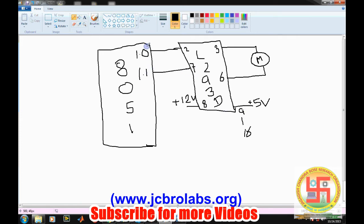Now, in order to decide what should be sent to these pins of port 1, we know pin number 1 and 0 have been connected to the microcontroller. When we send 1 here and 0 here, plus 12 will appear here and 0 will appear here, so the motor will run in one direction. If we set command 0 here and 1 here, this polarity will change. At that time, when 0 is at this pin and 1 is at this pin, plus 12 will come at this supply and 0 will come here. So the motor will run in the opposite direction. This is simple. We just need to change the signal which we are providing to these ports.